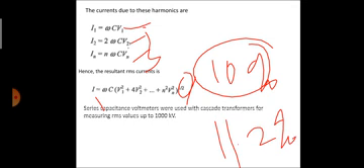Instead, series capacitance voltmeters, what we are talking about here, were used with the cascaded transformer for measuring RMS values up to 1000 kilovolts. The series capacitance was formed with the help of two parallel plates, as a parallel plate capacitor between the high voltage terminal of the transformer and a ground plate suspended above it.